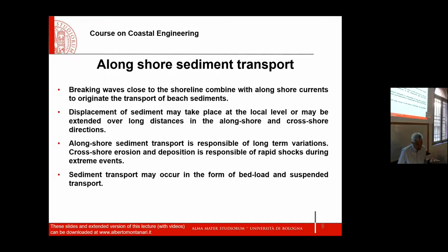But the assumption is reasonable, because with no waves, no energy, there is no sediment transport, and if I have high waves, very quick waves, I have more potential erosion. Why? Because there is more energy. And this implies that in order to translate this assumption into a model, I have to compute the wave energy, and in some way relate this wave energy to sediment transport. But before I move forward, let me say